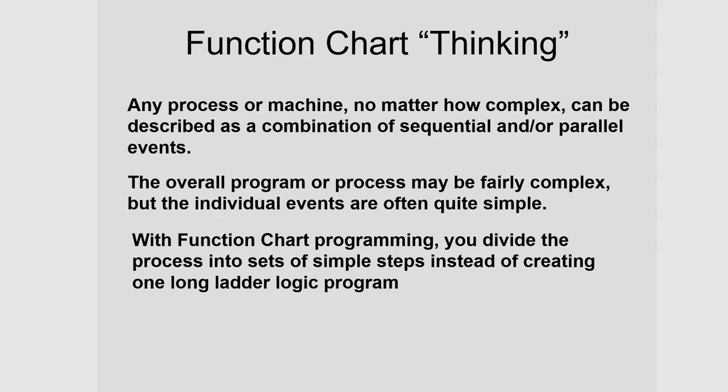Now that's pretty important. You can take the most complicated process that you can think of, and it can be divided down into just some simple, either sequential or parallel events. And function chart programming takes its cue from that.